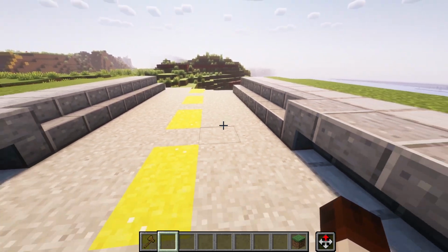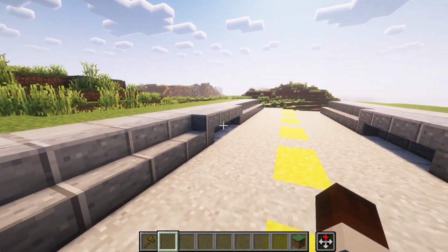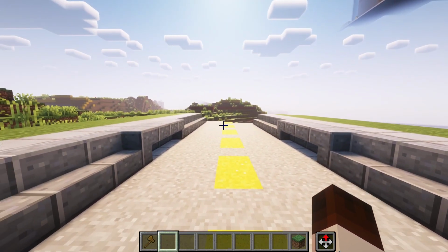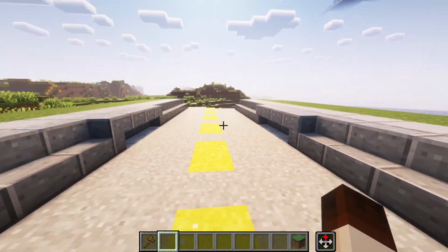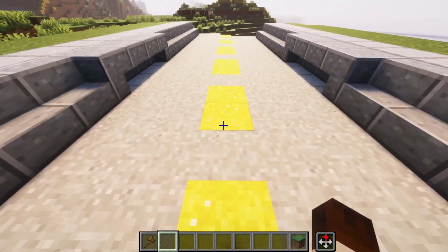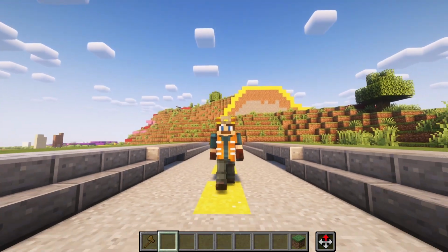And if you don't remember from the last one, we also have a cross section of a road, and roads actually do have about a 1.5% slope in each direction, so the water should never puddle on the crown or the center point of your road.